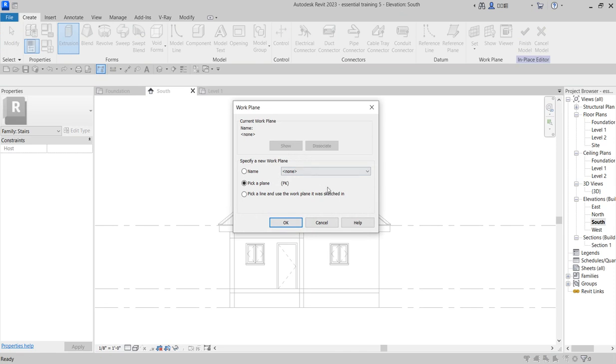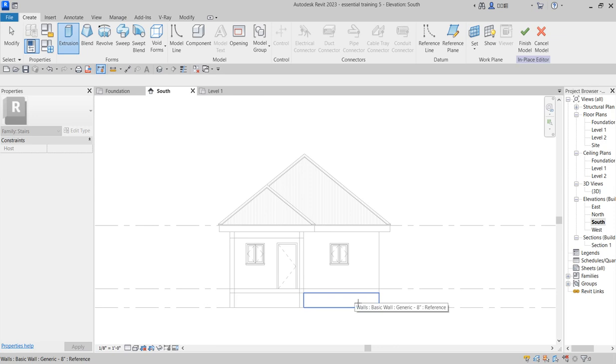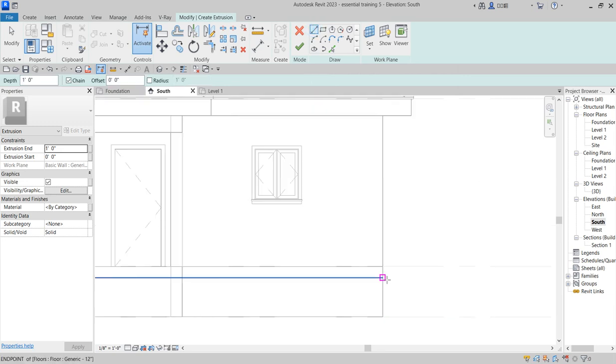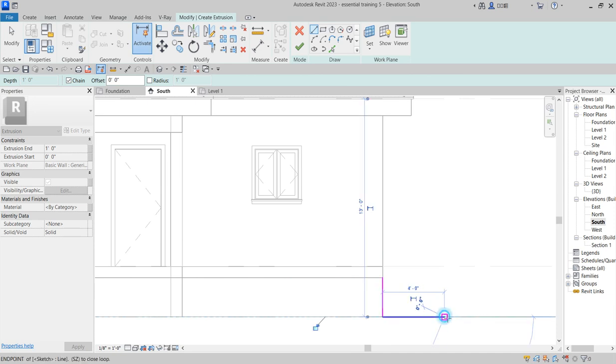Extrusion, when it comes to you, you do not click anything because you don't have any reference plane. So you want to pick a reference plane, which is going to work for you. You now begin to bring your mouse around this space. Anywhere you see that the rectangular place is snapped, you click on that. That is the plane for your drawing. From there, it has already picked that plane for you. Then you are creating your steps one after the other in that way.